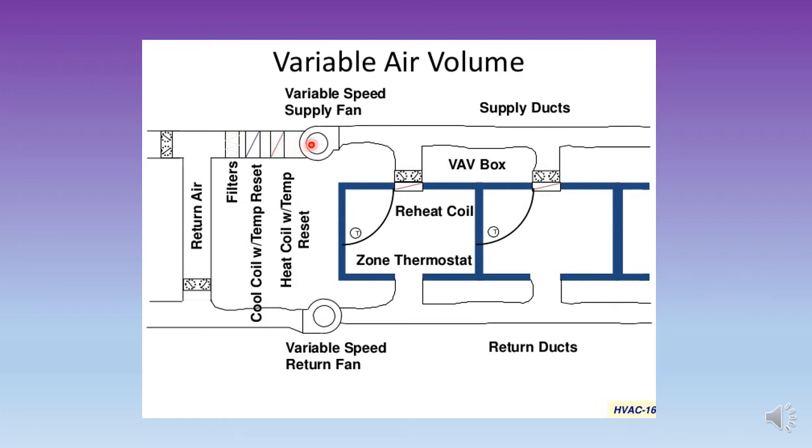And this is the supply fan, and because it is after the cooling coil, it is known as a draw-through fan. Draw-through fan, and the air will be blown into the supply ducts, and basically this is the space.